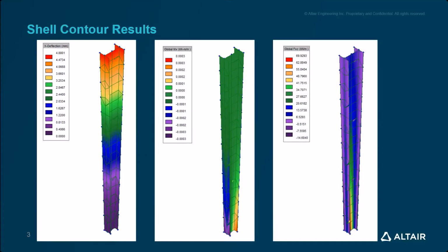So meshing some of those tapered sections can let us understand a bit more about what's happening with them. And since there's no regular shape along all the member, having the option of seeing this in so much detail could add a lot of value when looking at and validating the results. And since unfortunately at the moment S-Frame cannot perform the code check on all of those tapered sections, this could be a good way to make sure that our taper proposals for our projects are working just fine.